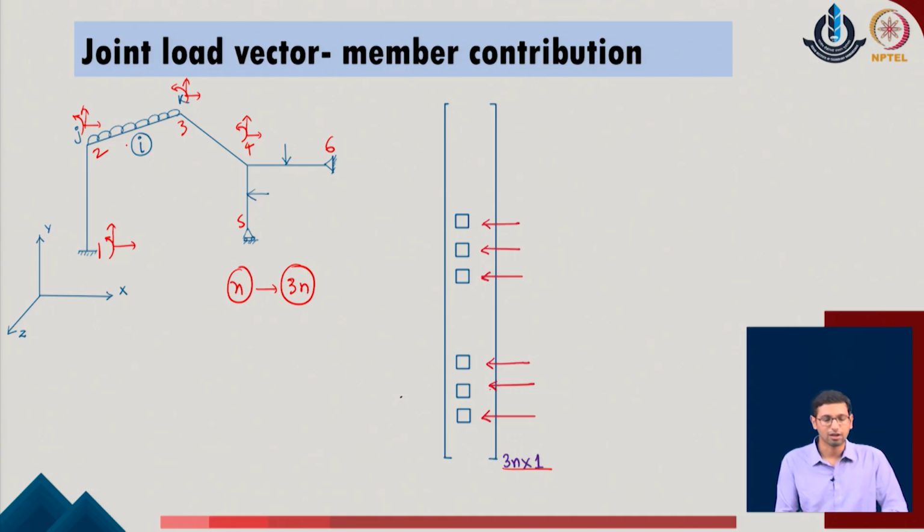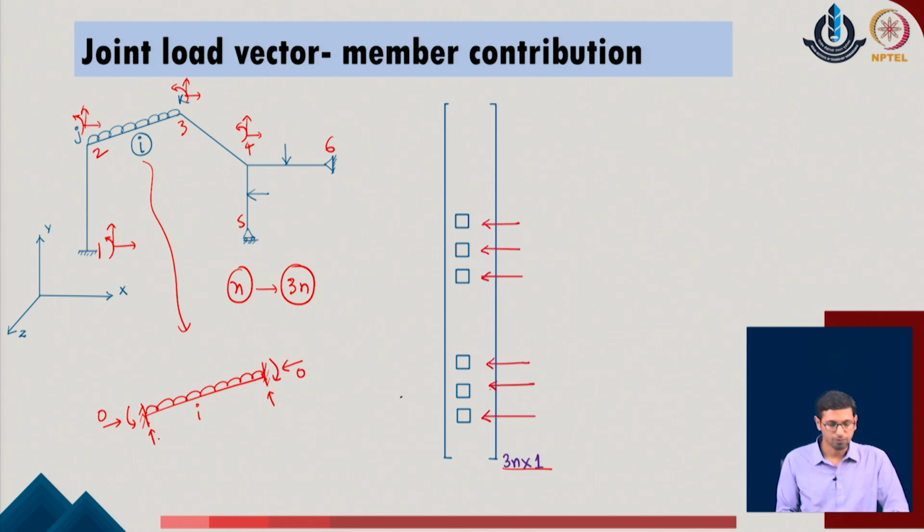Now, as we have done the calculation earlier, to calculate the load contribution, we said that if you bring any member i of the given system, the ith member is connected to two joints, say joint J and joint K. We already got to know that corresponding to any kind of load, say if it is having a uniformly distributed load on top of it, we can calculate the fixed end reactions of the given system. Say I can easily calculate these reactions of the given system. Also the horizontal components we are defining, so we will call that this value is 0, this value is WL by 2 and this value is WL square upon 12 in the given problem.